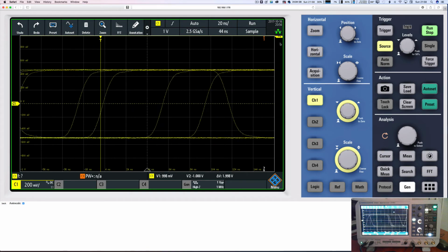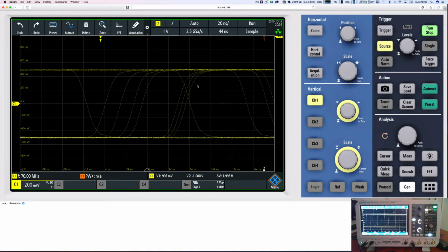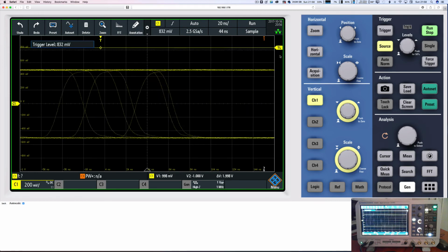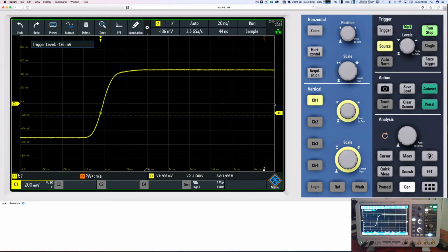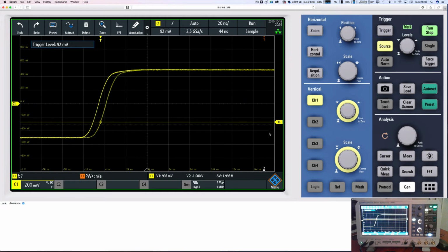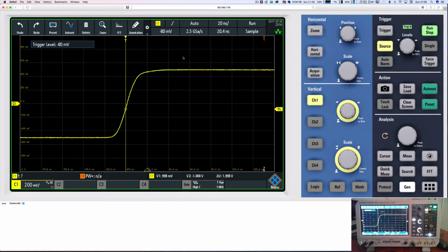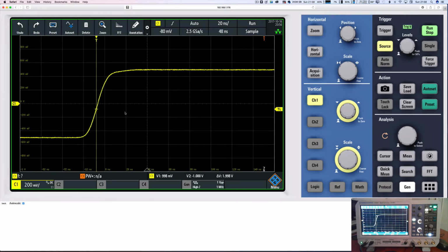Yeah, I know what's happened. I've moved my trigger value outside of my waveform, so the trigger is here. If I pull that down, you'll be able to see on the actual scope image and also on this that I'm moving the trigger. My horizontal trigger is here. I moved that previously, and I can grab that and move it away.